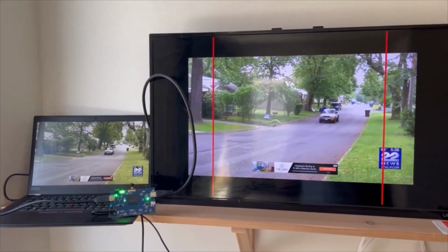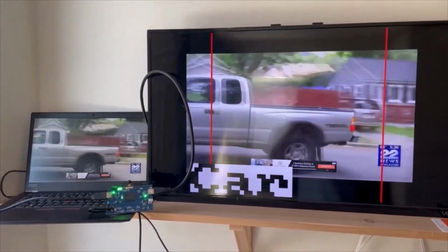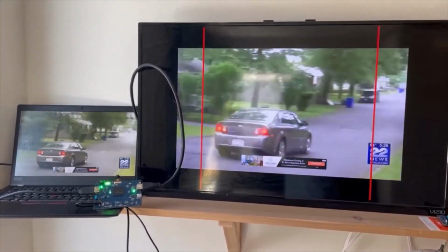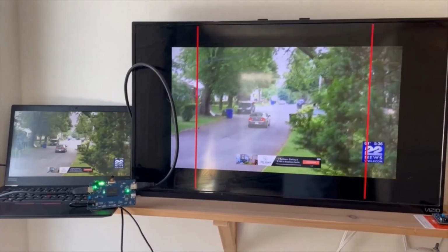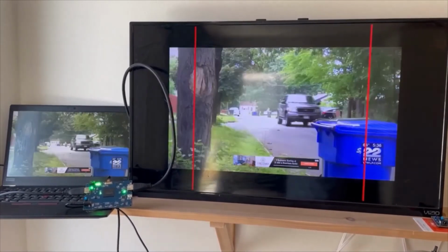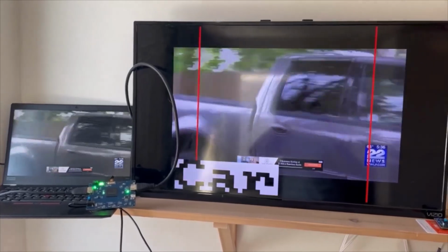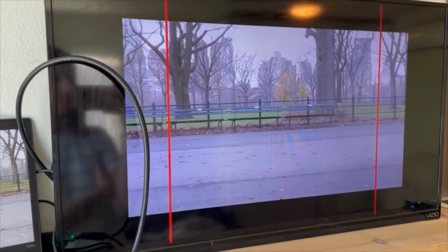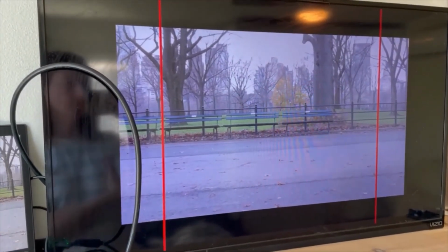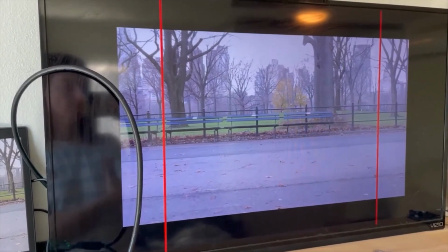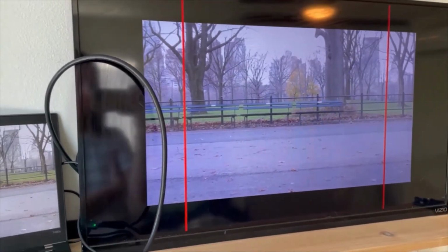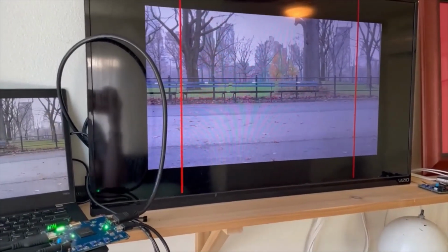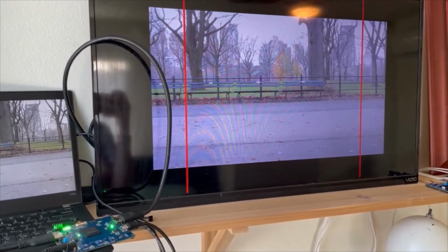HDMI input is available on the GW2A series Go AI 2.0 development boards, and is not included on the GW1NSR4 development board due to lower pin count. However, the object classification for cars and people is provided with a camera input for the GW1NSR4 and is just as able to perform the same classification demo as the larger devices. So for development purposes, we provide these larger boards with HDMI input for better debugging.